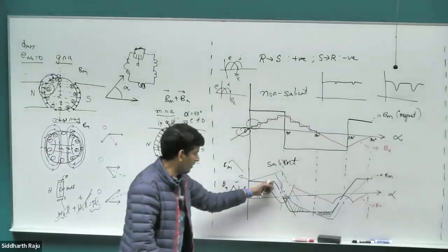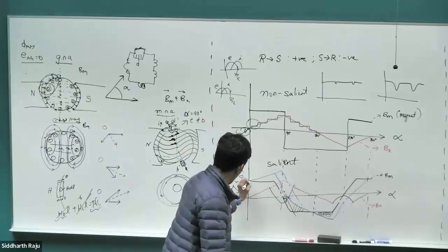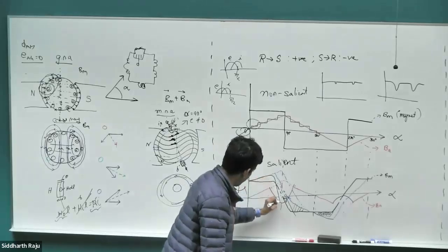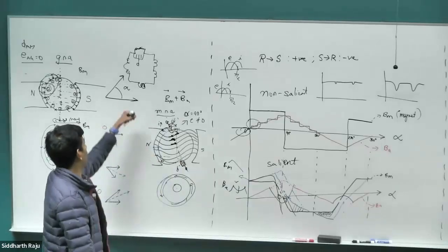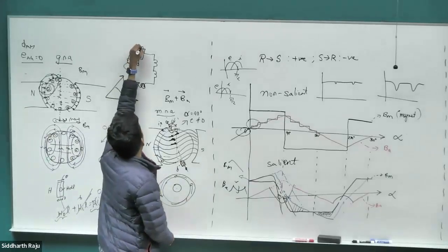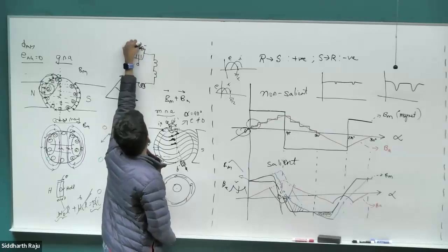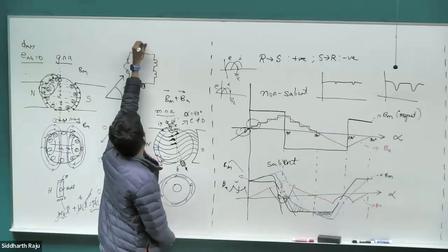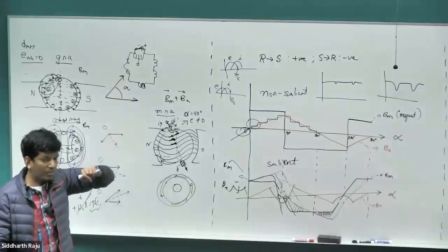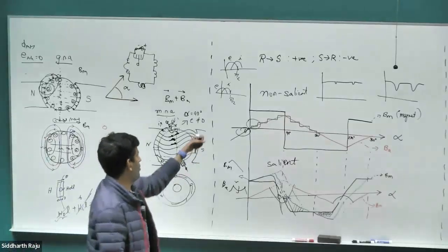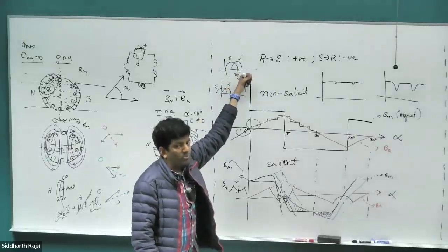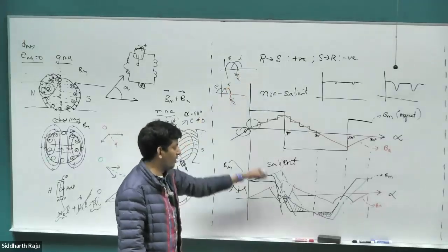Right? So that the sum of it, this and this waveform, the blue waveform, actually goes to 0 even earlier than 90 degrees. So what in effect you're doing is putting a coil here, which was previously positive or negative here, but flipping the direction now, making this negative, this positive. So it is creating a voltage that is countering the current that's in the coil, so that you can bring the current down much faster. You do not have to wait past pi by 2, but even before that, you can bring it down to 0.